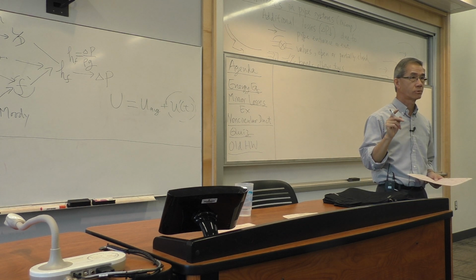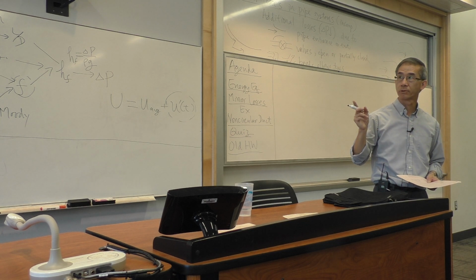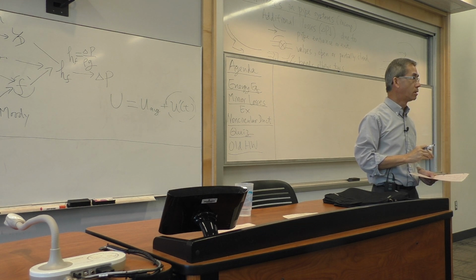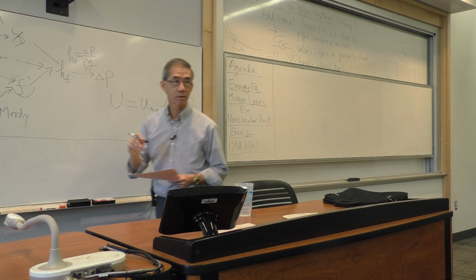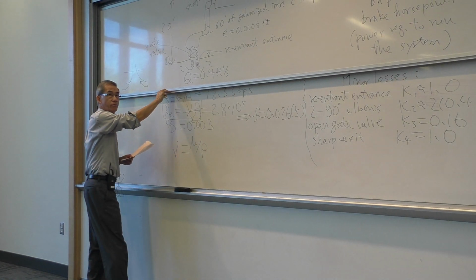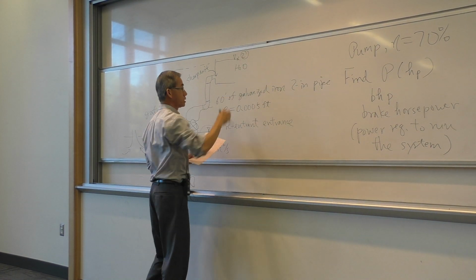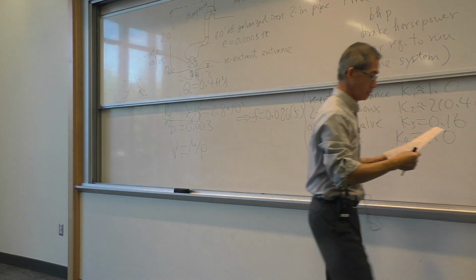I hope this is a trivial question. Because for the energy equation of point 1 and point 2 on that diagram, where do you pick point 1 and where do you pick point 2? I hope this is the obvious answer. 1, far away from the intake, not influenced by the pump action. And 2, always, again, far away from the exit. So my energy equation